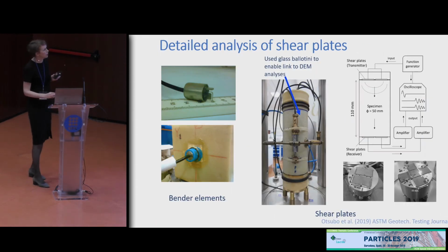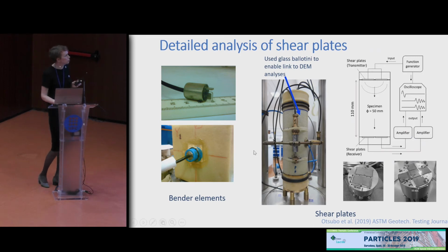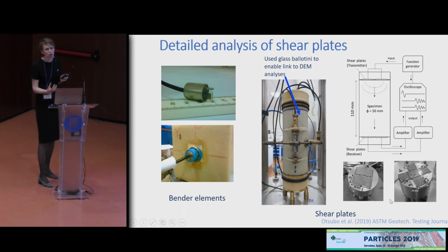So realizing this issue with using a point source, especially when you have coarse sand, we started to work, during Masahide Otsubo's PhD, on an alternative way of generating stress waves in a geotechnical lab, and that is using planar piezoceramic elements. So again, these can introduce a small disturbance into the soil, but they act over a larger area. And we looked at different configurations of shear plates to understand how this technology could be used and what were the limitations of its use.